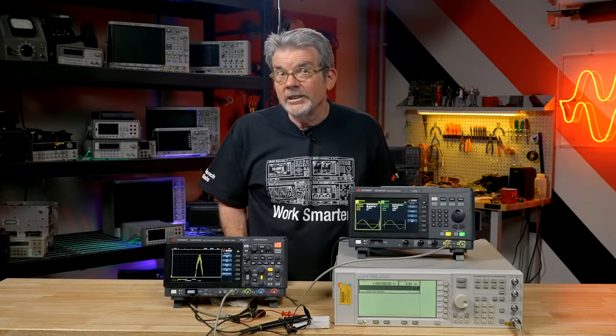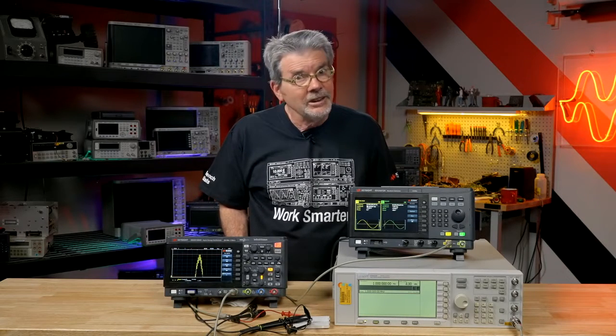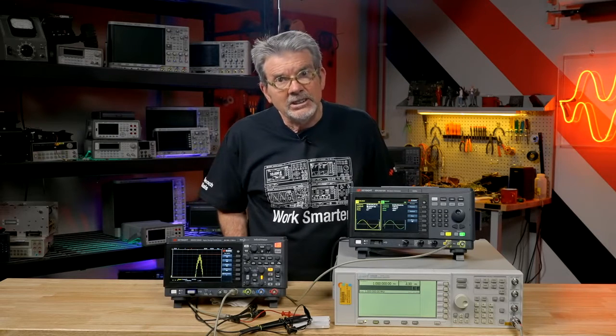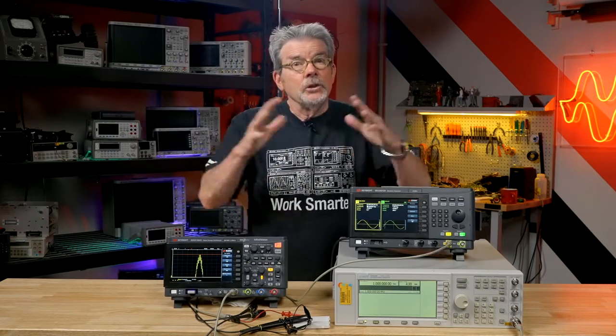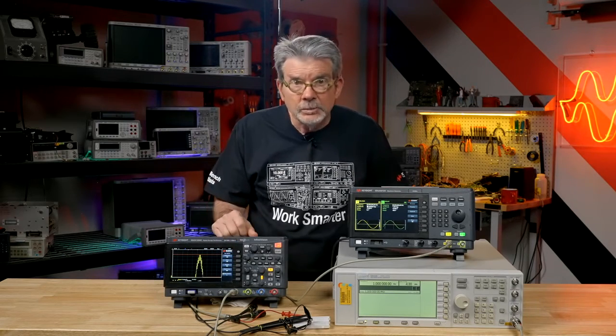So we just talked about and demonstrated bandwidth, sample rate, and vertical resolution, or ADC bits. But there are a few other specifications I would like to briefly cover. Memory depth, or maximum acquisition memory, can sometimes be important. The more memory a scope has, the longer time span it can capture at its maximum sample rate. This scope has 2 million points of acquisition memory, which is probably more than enough for your experiments as an undergraduate student. Some higher performance scopes, as well as higher price scopes, have gigabytes of acquisition memory.